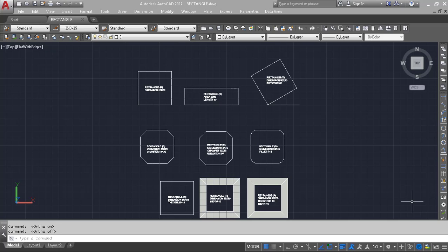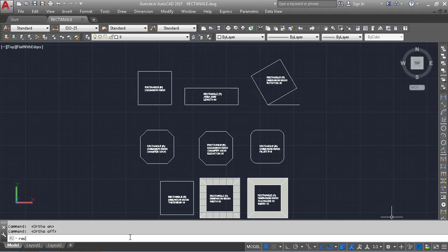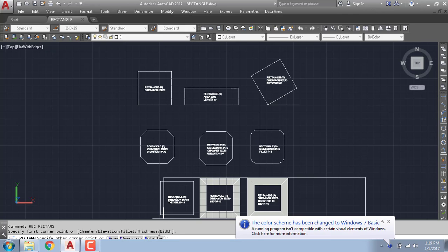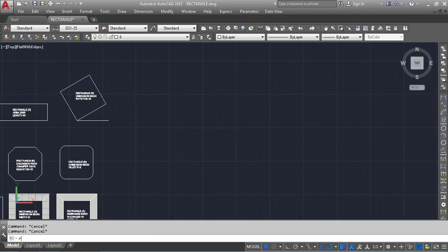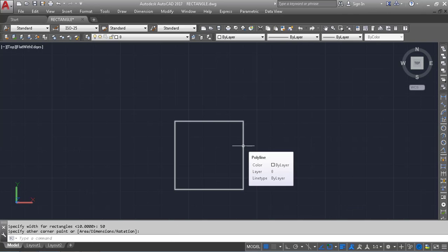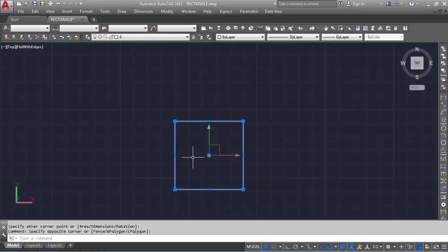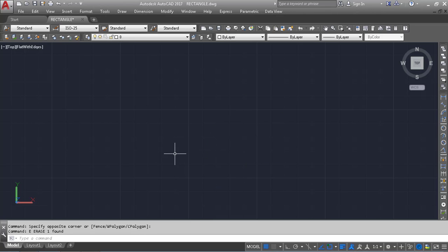For example, if you go into the rectangle tool, REC enter, there are several sub options there, and if you go into any one, for example I started making a rectangle, then again there are 3 sub options. So what are these and how can we use them? Normally people use REC enter, and put the dimension 50 by 50, enter, and now this is the rectangle. About 90% of people use just this much of the AutoCAD command. After that they do not use anything else. So today I am going to show you what these sub options are.